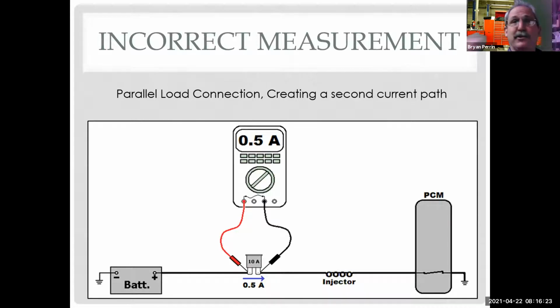He understood what we talked about with parallel circuits, and he goes, whoa, wait a minute, Mr. Bryan. Couldn't I just hook it up like this and figure out that what I see is half if the resistance is the same? And you're right. From Ohm's law, it would be half if the resistance is the same. The problem is we don't know the resistance would be the same, and I'm trying to get information for testing, and I need to know I'm correct. But in theory, yeah. So I love it when students bring stuff up like that because that tells me they're taking what we've already learned and applying it to something new we're learning and asking questions.